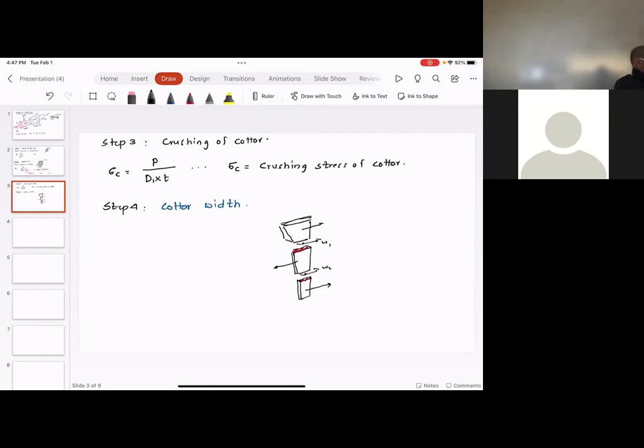If there is no taper, then maybe a little bit wobbly motion of the joint can throw that quarter off. That's why the quarter is taper, and then you hammer the quarter in so that there is a rigid joint between the spigot and the socket.